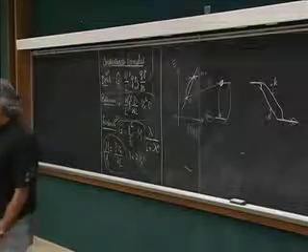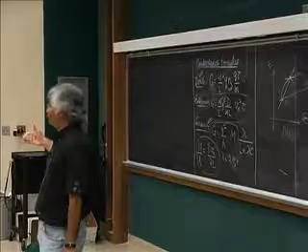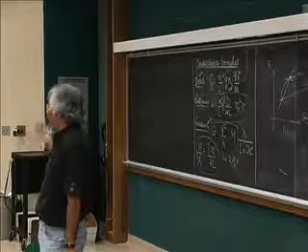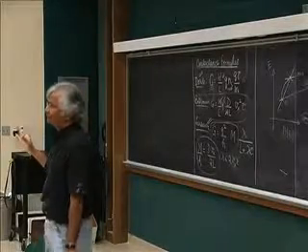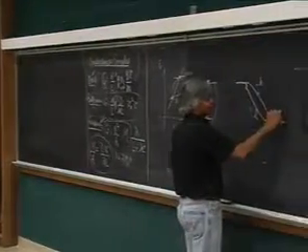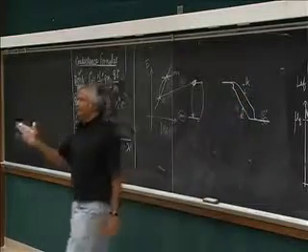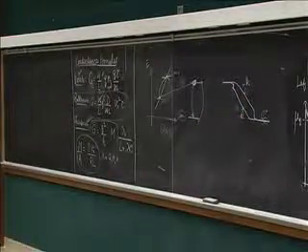The argument really is that you have 10,000 modes or 1 million modes in there, and the slightest difference is enough to carry that current. Because you had only 10 modes here and 1 million modes there, you only need a small fraction of this separation to carry the same current. That's really the essence of a contact.